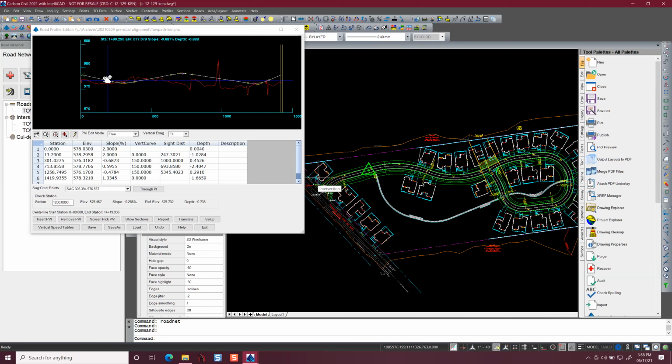Now here's my question to you from an engineering standpoint. What is it going to be like trying to build that road in the wetland anyway? Let's say we're going to minimize the impacts, of course, but what do you do there? Do you have to over-excavate and fill it back with an engineered base, or how do you handle it? What would happen is the geotechnical engineer is going to have to take a boring there and a sample of how deep the spongy soil goes, so I know how much overburden to excavate.